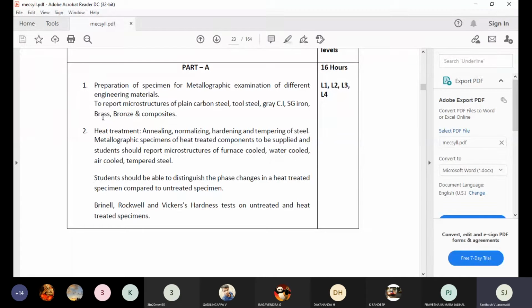You know very well how the brasses are manufactured and processed, and how the bronzes are processed. The combination of copper and zinc, we call brass. The combination of copper and other elements, such as tin, mixed into the copper, makes the copper become bronze. So these are the alloys. Now, through the microstructure we can tell them apart. Let me tell you the importance of the microstructure.